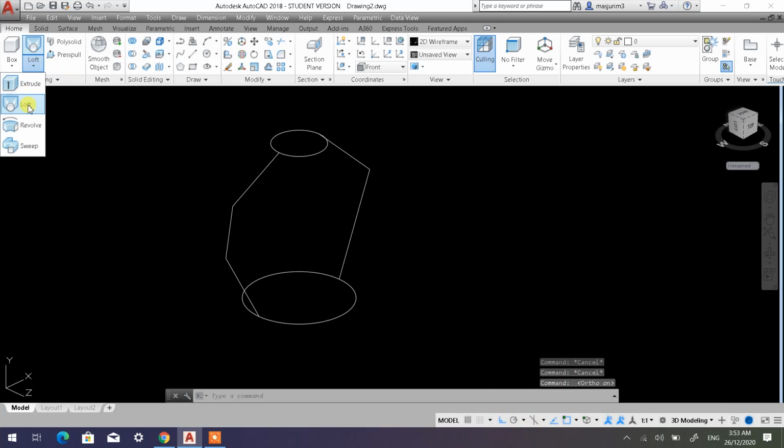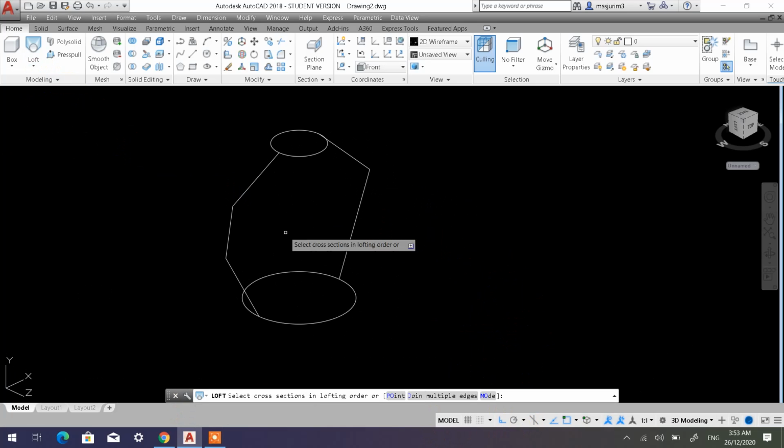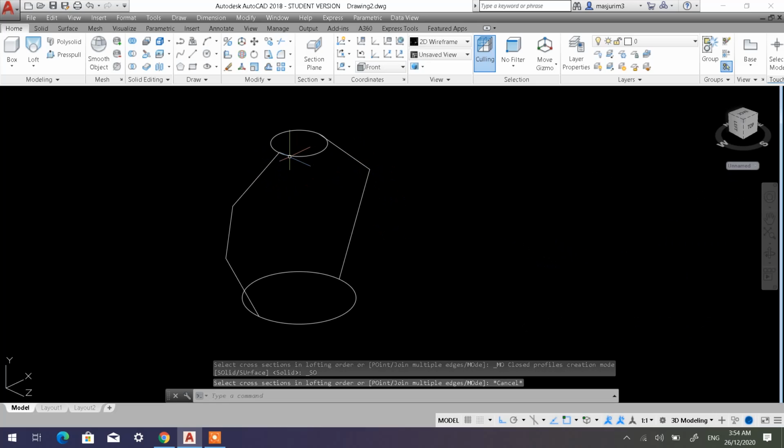So I'm going to proceed with my loft. You remember that the guidelines must touch the side portion, anywhere, any point, but the side portion of each of the related sketches. It must be correct. For a path, it must go from center point to center point, regardless of the shape of the sketches involved, polygon or whatever shape. When I'm talking about a path, it must go from the center point to another certain point, and if there are more, to another certain point, to the center point, and so on. But for guidelines, it needs to touch.